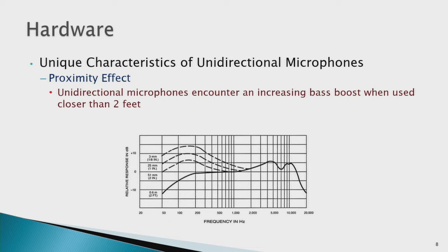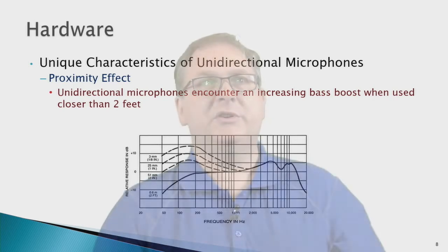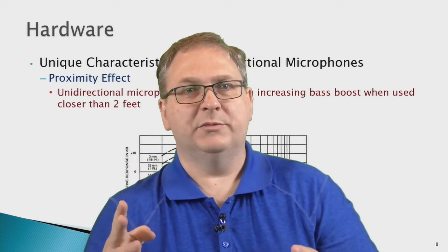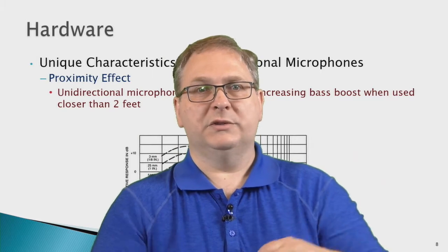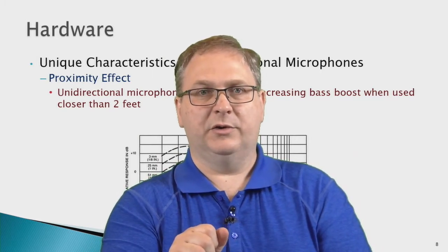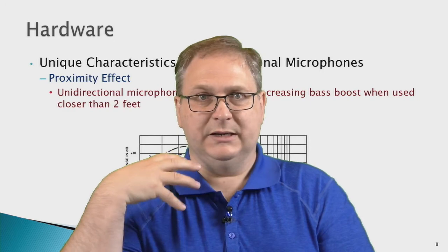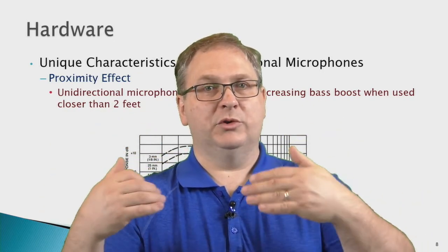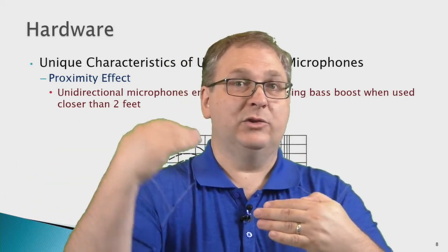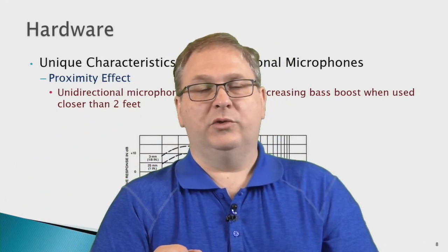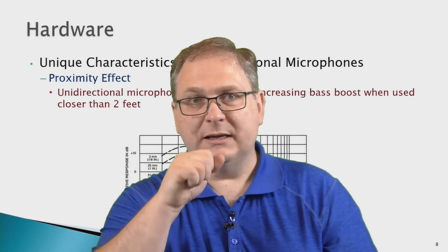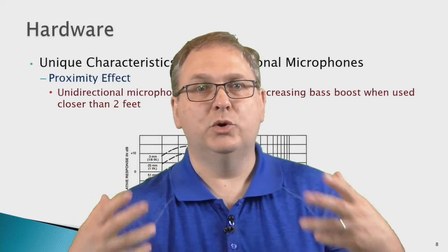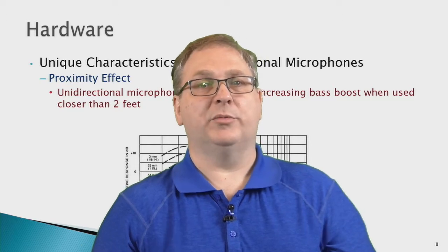As you get closer in terms of distance, you notice that it is higher, and that higher amount represents about 4 times the volume in low frequencies. So in other words, if you're using a microphone and you're bringing it closer and closer, you actually get a boost in that bass energy. Not just a boost in volume, but a boost in volume and in those bass energies. So if you notice that when people are using microphones, as they get closer to them, it sounds boomier and boomier, that's because of the proximity effect.